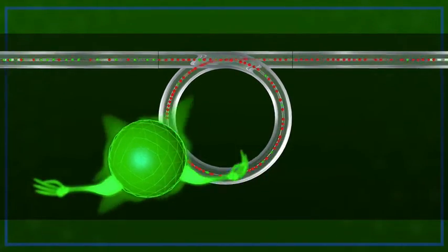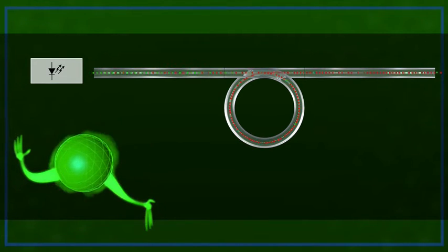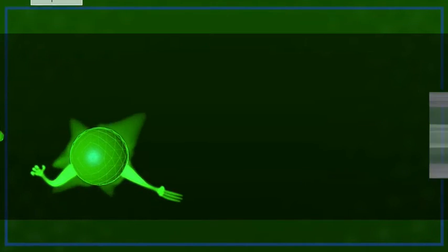To pump this device, an optical laser diode can be installed on the pump end. Because such a laser is single-mode, its power is limited to the output of a single-mode pump diode times the quantum efficiency of the laser. Single-mode pump diodes are expensive and relatively low-powered. To achieve higher power, either more pumps need to get connected to a fiber, or the fiber will need to get much fatter. In fact, over time, both came to be.